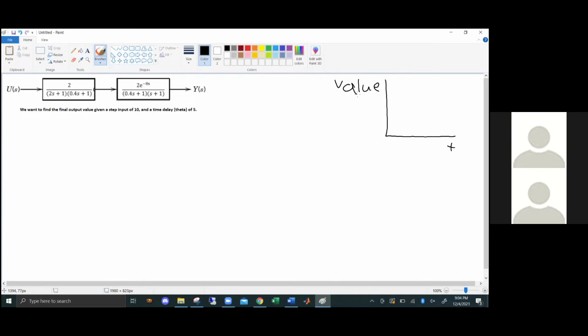So let's get started. We chose to model a simple two-transfer function process with a time delay. We are using these transfer functions to model the response of a parameter change in a mixing tank. Before we get started in Simulink, we want to figure out how this process will be modeled by the transfer function. Let us start with a step input. A step input indicates a set change in a parameter at a certain time, which continues for the remainder of the process. Parameters that can change include temperature and level in the reactor, to name a couple. In this transfer diagram, US represents a step input.